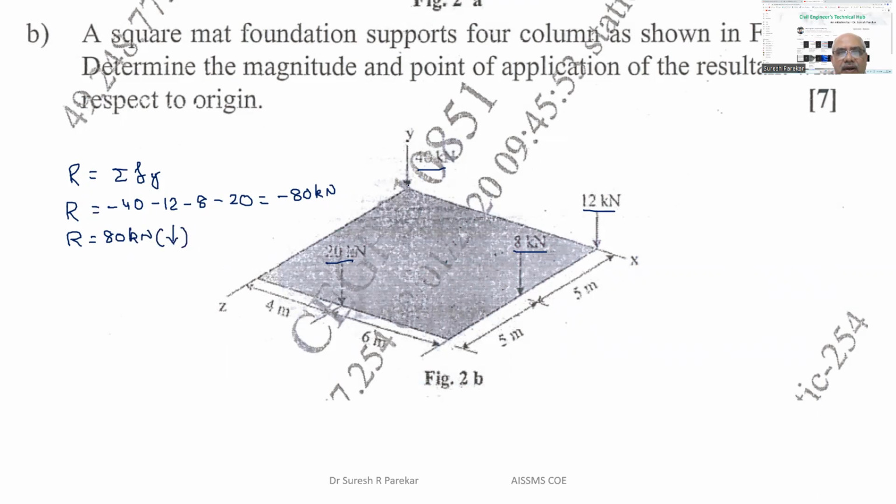Now, if we see the coordinates, so if I say this will be force A, then this is again the XZ plane. So my Y coordinates are 0, because vertical is Y and your plate is in the XZ plane passing through origin, and therefore all Y are 0. Here we have origin, so we have all 0. Then 12 is on the X-axis, so we have Y and Z 0. Parallel to x, we have distance 4 plus 6. So x is 10, y 0, z 0.